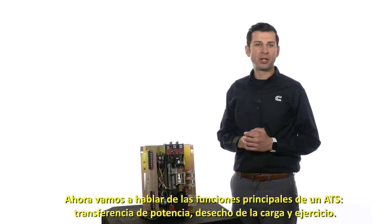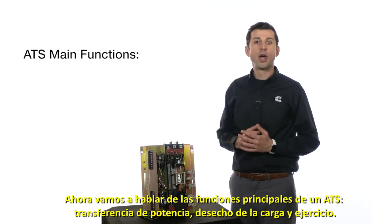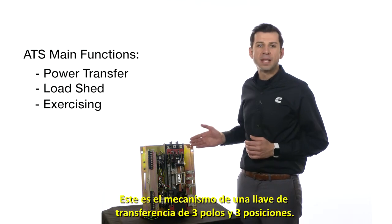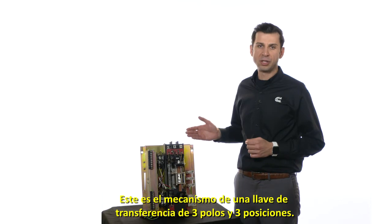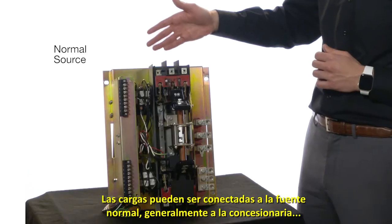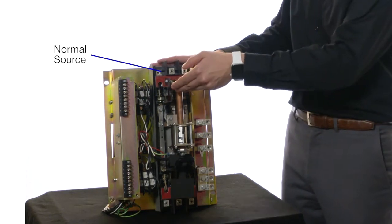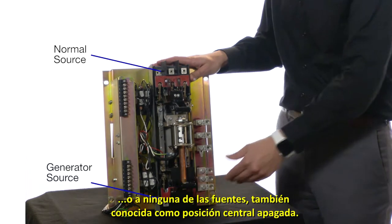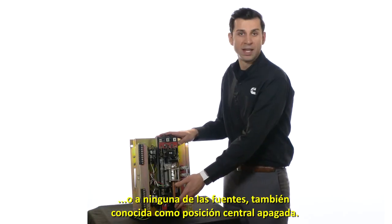Now we'll talk about the major functionalities of an ATS: power transfer, load shed, and exercising. Here is the mechanism of a 3-pole, 3-position transfer switch. The loads can be connected to the normal source, typically the utility, or to the generator source, or to neither source, also known as the center off position.